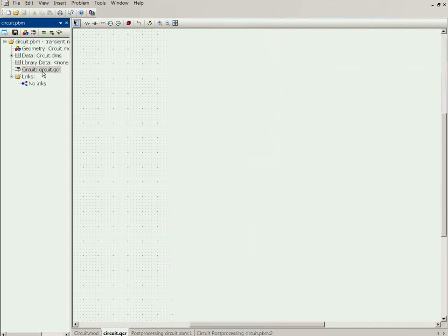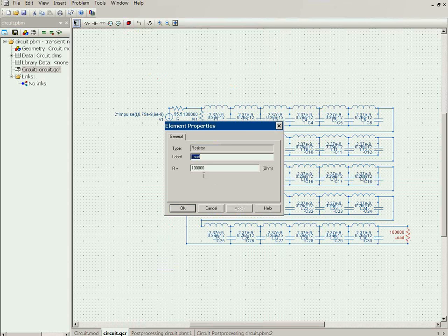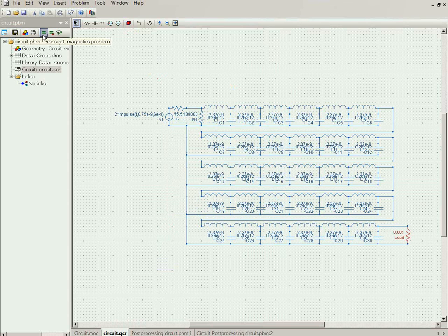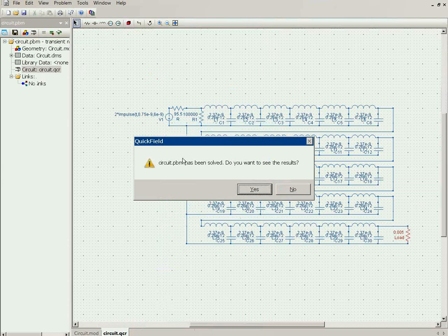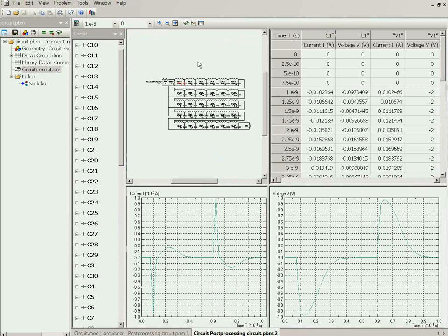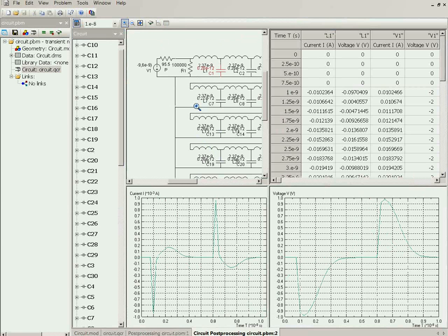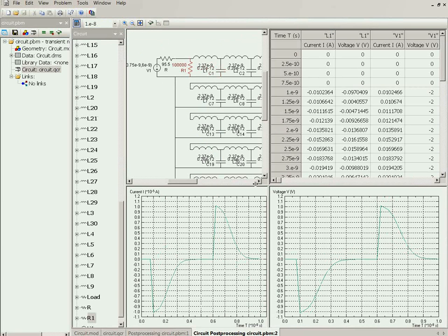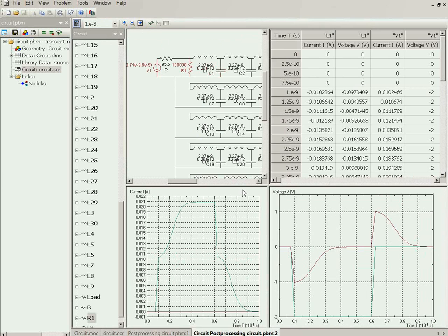If we have the shorted load, the reflection again is 100%, but it has the negative value. Let's again measure. You see again, the voltage was initially shot at 1 volt, but then the reflection came and the voltage dropped to 0.